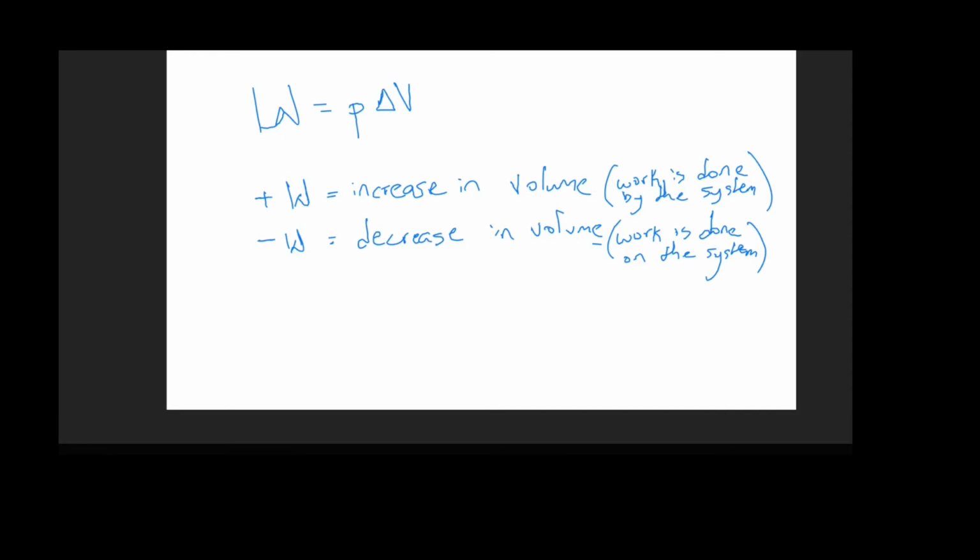When you calculate the work done by gases, you have to note if it's positive, you just write the positive number. But importantly, if it's a negative work done, you have to put the negative in the answer given. And you'll know it's negative if the volume decreases. If it starts at a higher volume and then goes to a lower volume, then we know that it's negative work, and hence you have a negative answer.